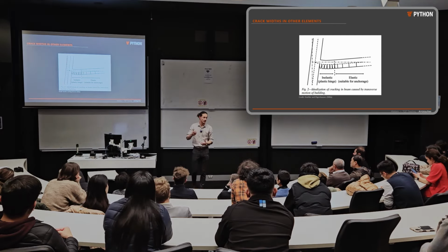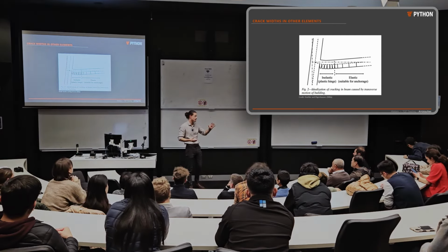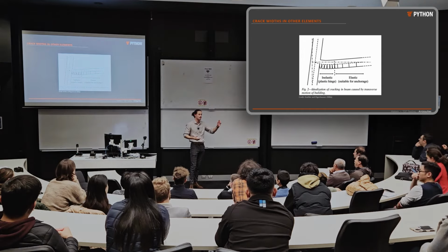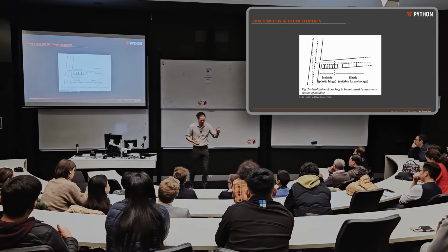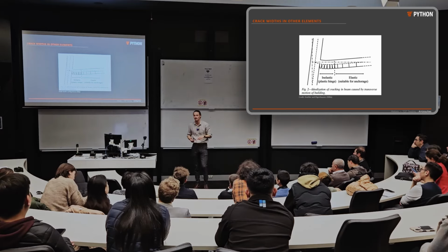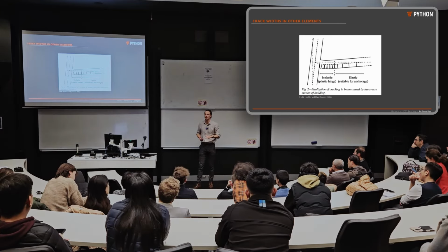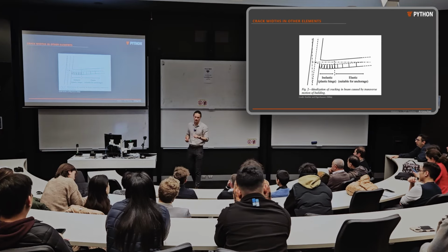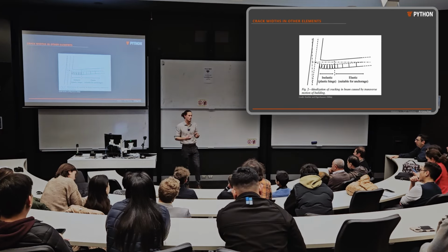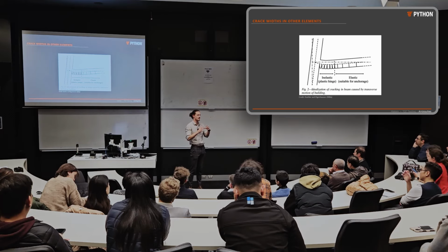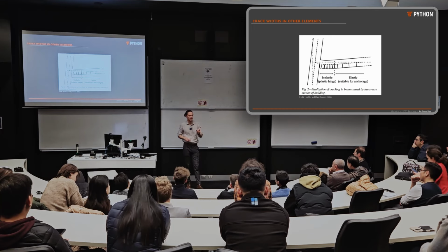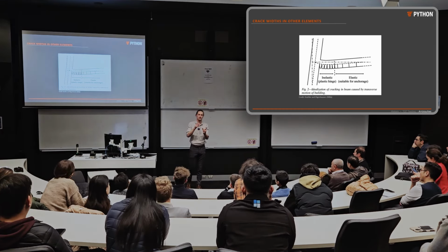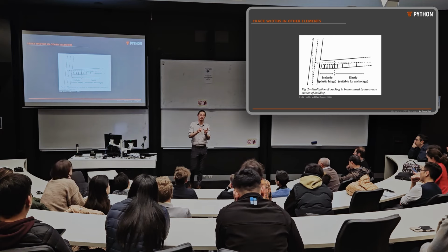The thing to keep in mind is when you're thinking about a C1 capacity, fundamentally what it's allowing for is a 0.5 crack width. Now, the 0.8 crack width, we do have documented justification for. The logic for that was that we should be rating anchors for the moment where a reinforced concrete beam reaches the stress where the reinforcing just starts to yield. And so they used empirical formulas to calculate the crack width at the stress that the reinforcing is about to yield.